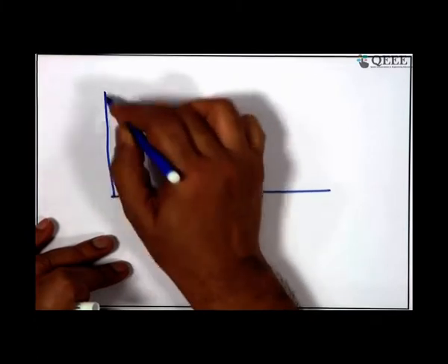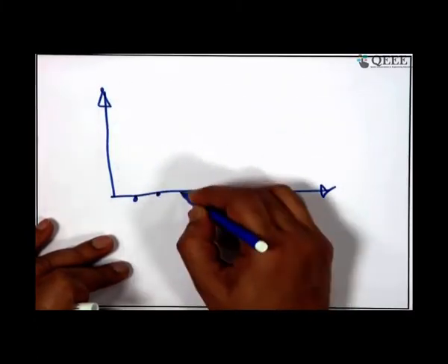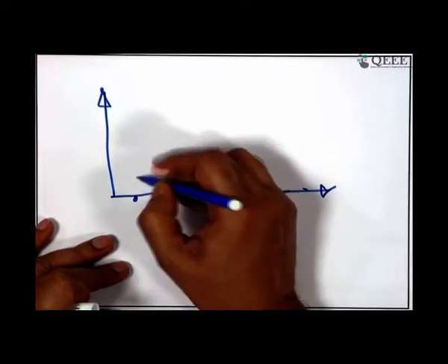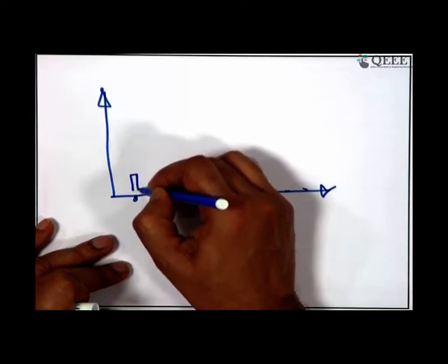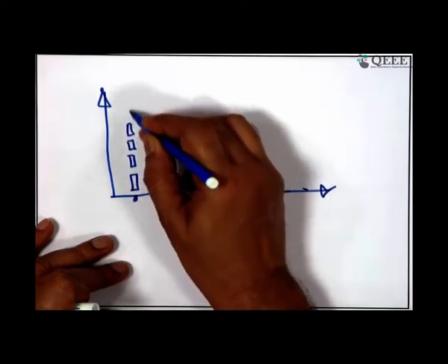That creates the problem. I told you there is a way out, that the development of the influence line is convenient for the engineers. They found it most convenient and it is represented like that. The other way, what we could have done, instead of the influence line, is to take different sections on the beam, and at each section indicate the values of the bending moment with a bar chart or some values as the unit load moves.